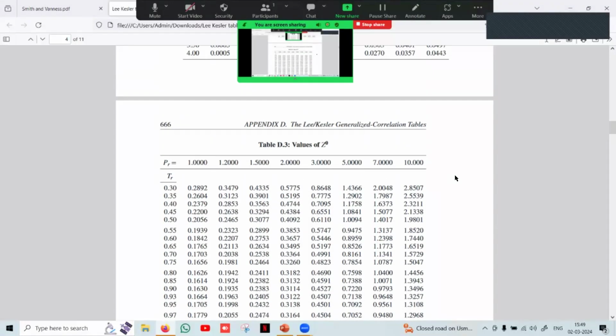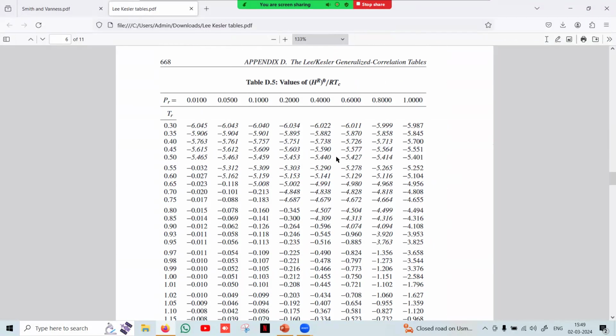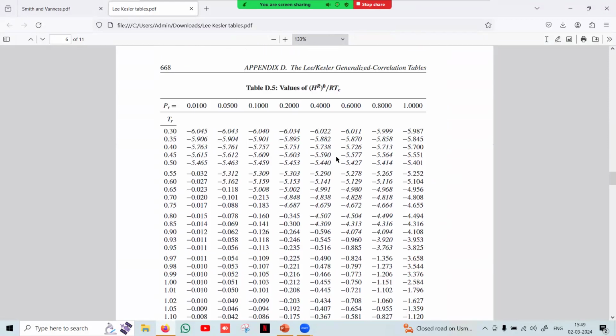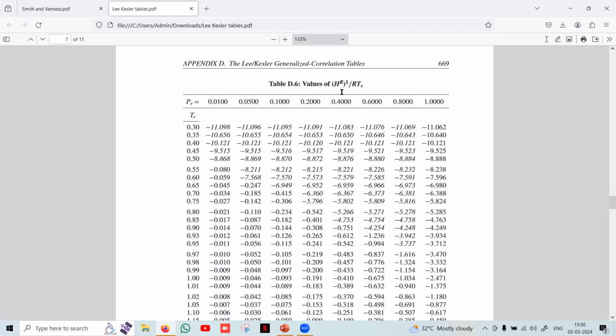So this one. So this was for the Z naught, Z1, and this again for HR naught by RTC. Okay. So again, you have to find the HR value, and you should multiply it with the TC here. So TC, which we have found here, is somewhere around 337 Kelvin. So you should be multiplying with that, and the R value also according to that, 8.314 that we have, right? So you can refer to this textbook which is available freely on the internet.